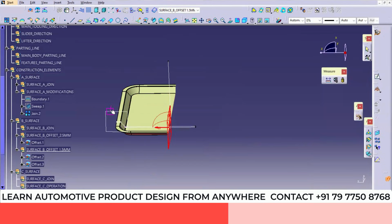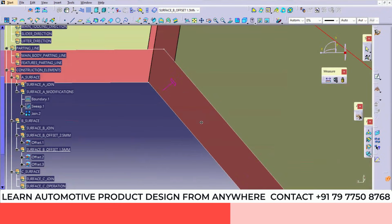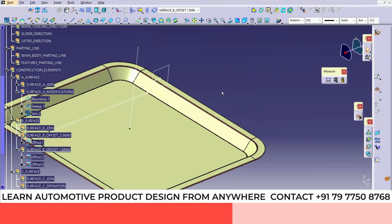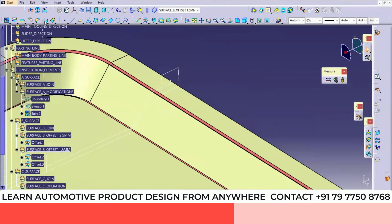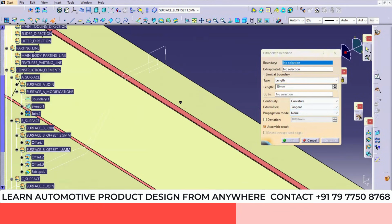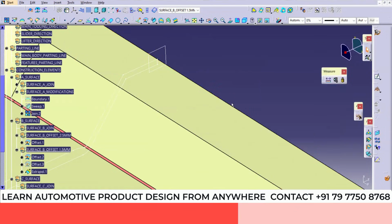Now if I cut the section, you can see this is matching 2.5 till here. Then this is also 1.5 matching, and this is also 1.5 matching, right? Now a single B surface is required, so we need a merging here, right? Merging means extrapolate, this time with curvature. Select this. 5 mm is sufficient from all the sides.